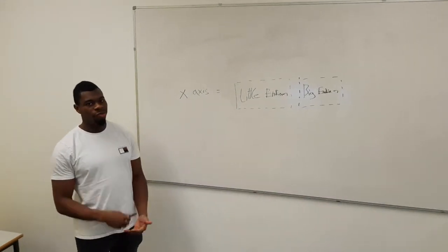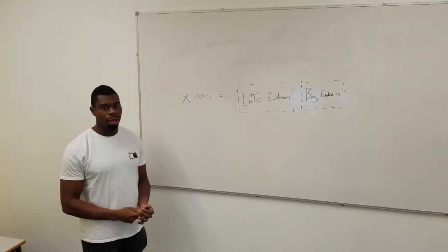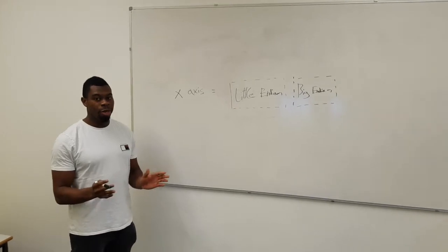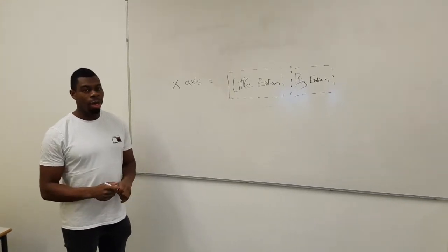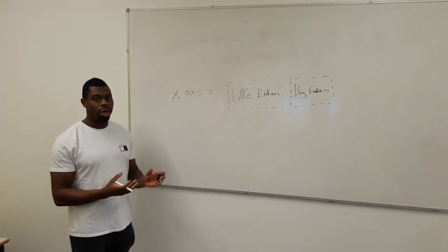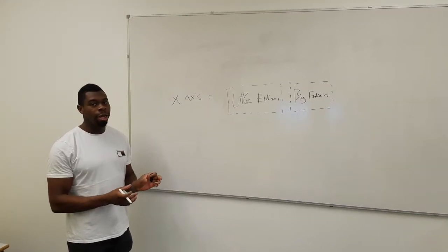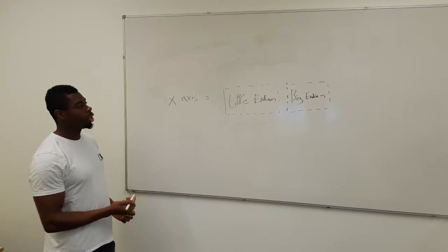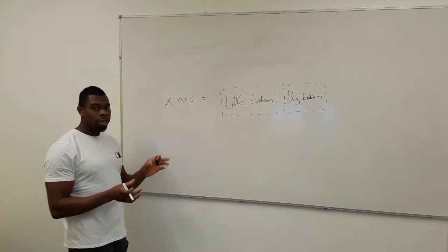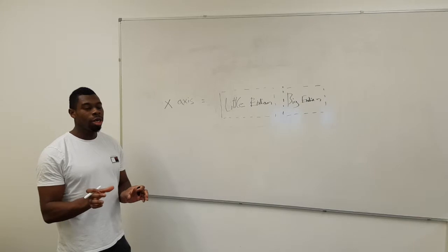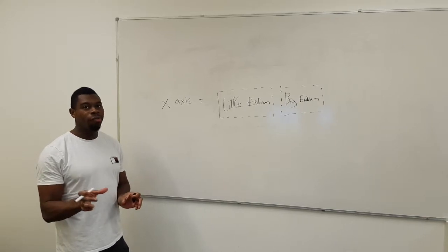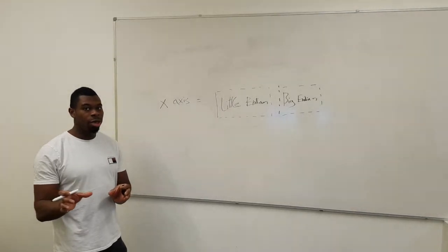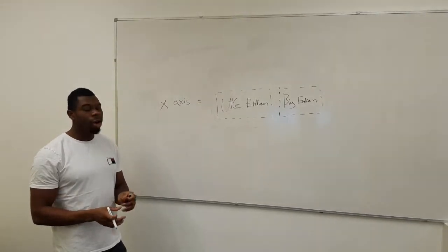So what we discovered when we first got the values from the accelerometer was that the sequence of bits was actually out of order, and then after some research we discovered that it was essentially running as a little endian, and not big endian. So what that means essentially is the sequence of bits have been shifted, meaning the most significant bit is in the least significant portion, and vice versa.